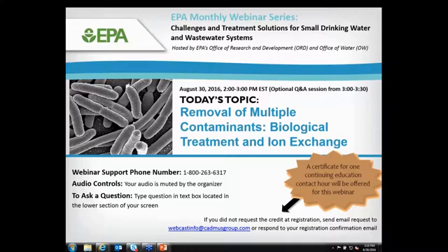The question asker could email me and I could send some of the data. I don't have the number right now, but we are measuring that because in places like Florida, sodium has a primary MCL, and so that's one of the balancing acts of this process: making sure that as you remove hardness, for example, you don't exceed the sodium level. That's another reason why we've looked at alternative salts like potassium chloride on the cation exchange side and sodium bicarbonate on the anion exchange side.